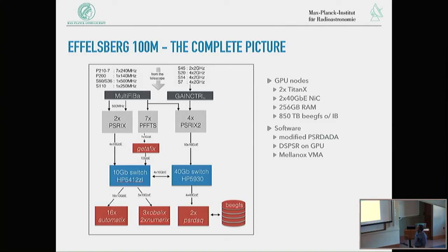These are the ROACH 1 systems, these are the ROACH 2 systems, and this is the bit that I was talking about, where you could configure the ROACH 2s in dual input mode, with the 5G ADCs, if I did not mention. So you can run these in parallel and process all 7 beams. This has turned out to be a very bad idea because of the very complex way in which you have to switch these signals in here.